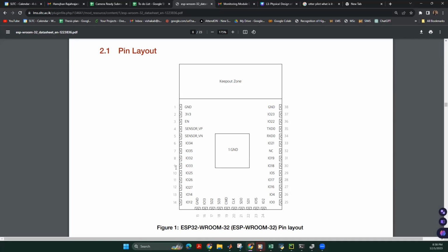So when we are enabling, for example, communication protocols such as SPI and I2C, we need a set of pins activated at the same time to do the communication with the other microcontroller, for example. The other microcontroller also needs several pins activated at the same time and connected to specific pins in the ESP32, to get the necessary communication done between the microcontrollers in a serial communication and in a reliable manner.